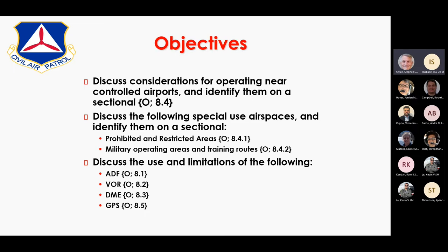We're also going to talk about 4 different kinds of navigational equipment. ADF is on this list. It's pretty much unusable because of lack of transmitting towers that are dying, but it's the mother of all electronic air navigation. It's a good starting point to orient people. We'll also talk about VOR, which is a more precise form of radio direction finding. DME, which is distance measuring equipment. It simply gives you a range in nautical miles from your airplane to a transmitting location. And then GPS, which is making us all lazy and lulled to sleep.